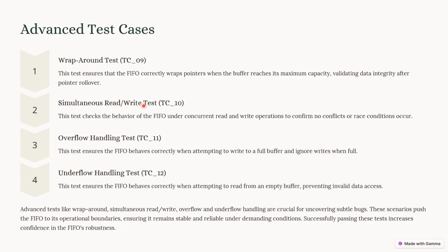After that, simultaneous read-write test. Through this test, we will check the FIFO behavior under concurrent read and write operations. After that, overflow handling test. Through this test, we will ensure that the FIFO buffer properly handles the data when it is full and ignores further write operations. Similarly, through underflow test, we will validate that the FIFO behaves correctly when attempting to read from an empty buffer, preventing invalid data access. So these are the key test cases that we will validate and implement in our design.